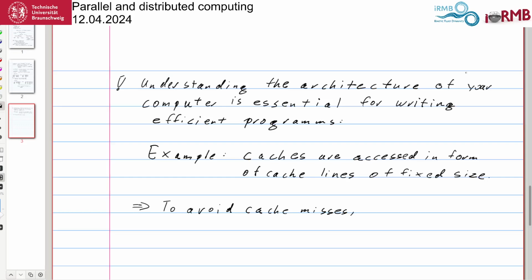If you look at the GPU, the memory is all around, directly built in, as short as possible, to reduce this distance, because it's expensive. In 1 gigahertz, you cannot go further than 30 centimeters.